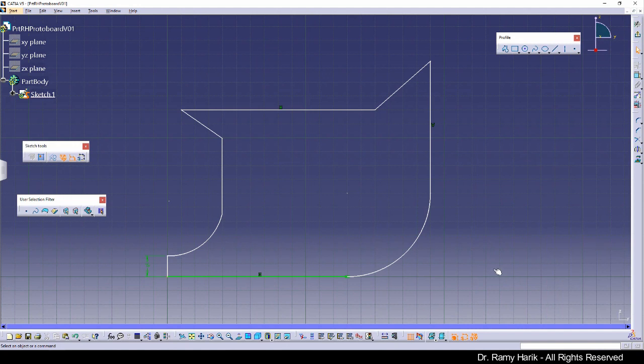Now, what we are trying to do is ensure that our sketch is ISO constrained. What does ISO constraint mean? It means that all the relationships are connected, and then you won't have a free floating sketch. So let's continue adding. In here we have the radius of 60. I'll select here, click on the radius, and we keep it at 60.